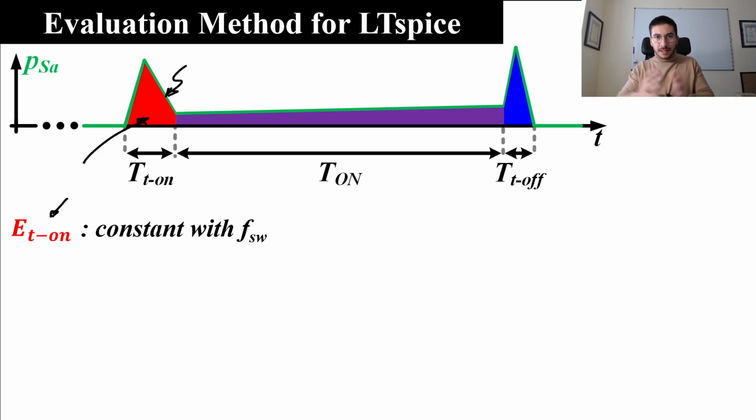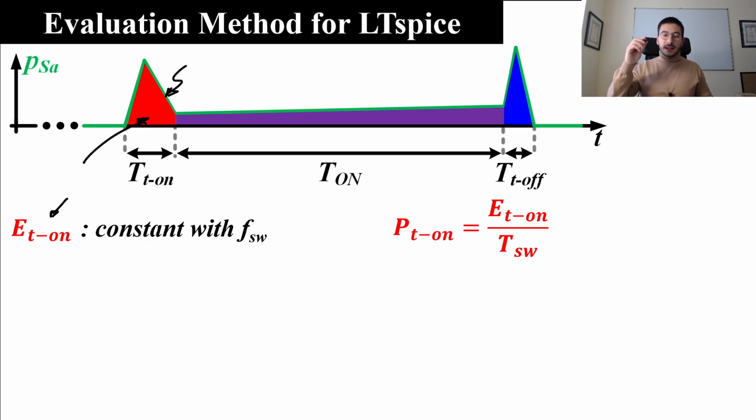So it's something that doesn't depend on the switching frequency. However, the turn on power losses depend on the switching frequency, because they depend on the period.